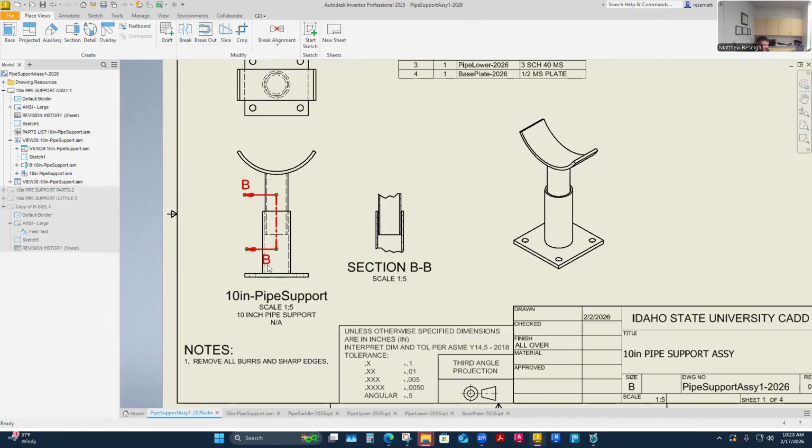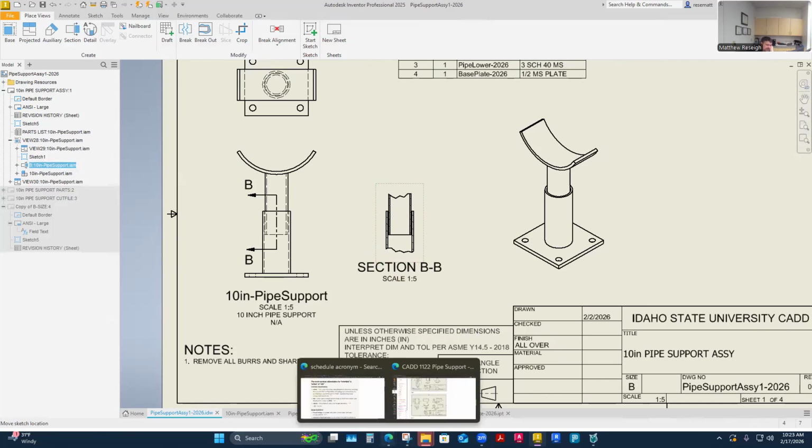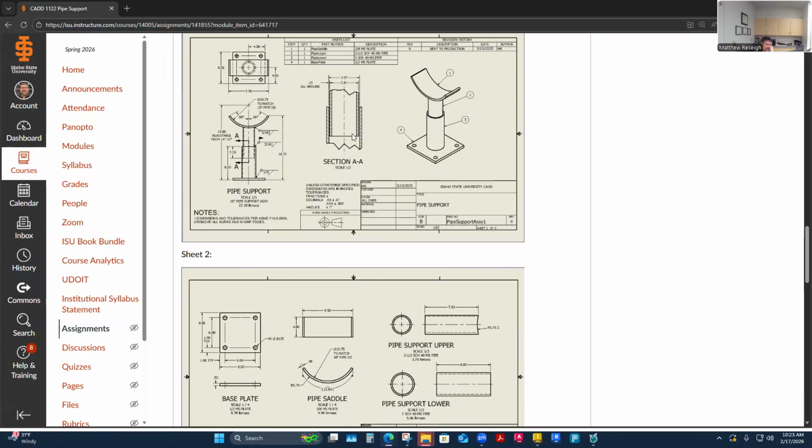Yeah, so all I had to do is just draw a line down for this type of section. If you try to draw that, I'm always trial by error, saying, oh, that's not the way I want to do it. It's nice to get that on there because they do take up a fair amount of room, and so you'll know where you want to put your weld symbols. Technically, I could have sectioned the other way too and dropped it over here. By default, they're orthographically aligned. I think I end up moving mine out of alignment just to create some space. Yeah, I actually blew it up a little bit bigger, and it's definitely not in orthographic alignment, probably because of the space I had to work with here.